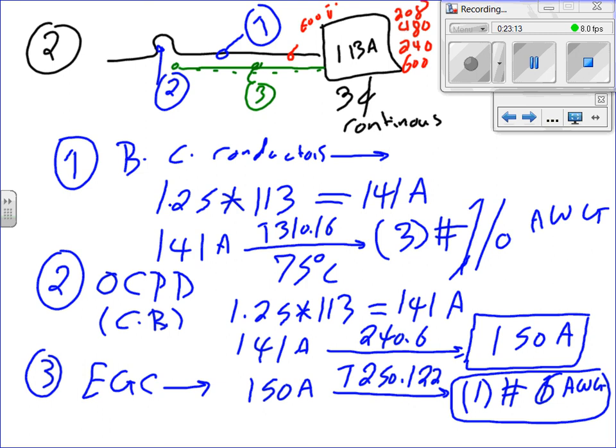The lower voltage, the safer. That's something in your mind. Your lower voltage is safer than higher voltage. That's a safety factor. So long story short, if I have my choice, and this machine is my choice in a building, I will wire the whole building with 600 volt and call it a day. Because the conductors will be smaller. I can pump more current in a smaller conductors, more power.